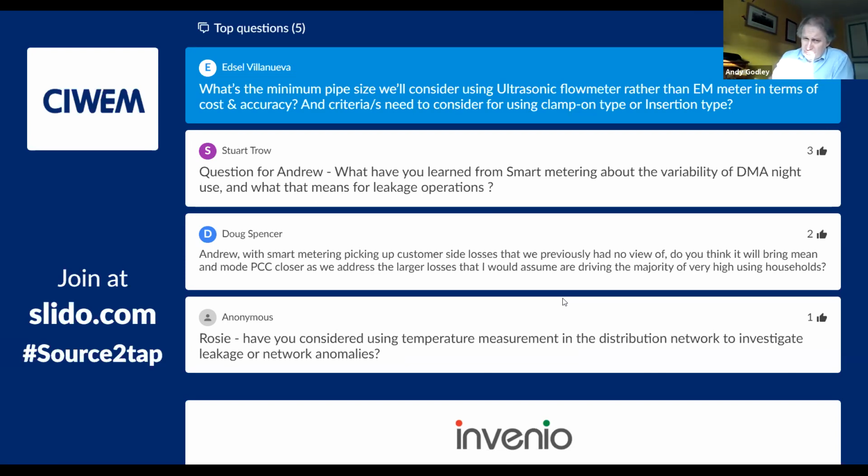So very, very large ones will tend to be insertion, and as you come down smaller, then you can get the spool piece types. But the insertion ones have the benefit that you can hot tap them into a live main rather than having to disrupt the main. So there's a whole plethora of issues to cover there. It's not necessarily quite a straightforward answer. But I think most independent specialists would put an electromagnetic meter in if they could, but it's hard to retrofit them because of the difficulties that you have.